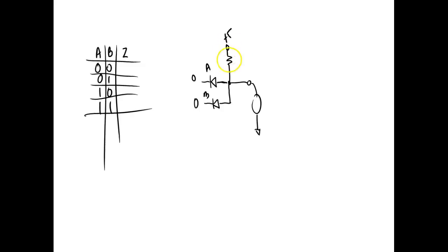It's going to be 0, yeah, and that's one of the resistors got to be there. So this guy's forward biased. Actually, it's going to be about 0.7 volts, but it's still going to be considered a 0, right? That would even be legal in TTL. In TTL, anything below 800 millivolts is considered to be a legal 0. So I'm going to put a 0 right there. Okay.